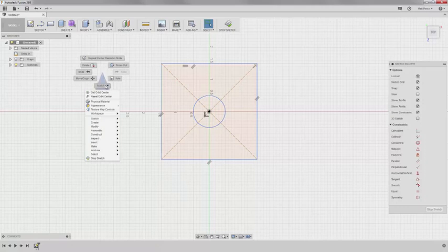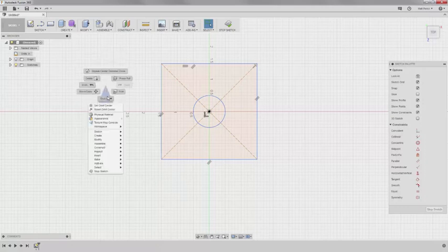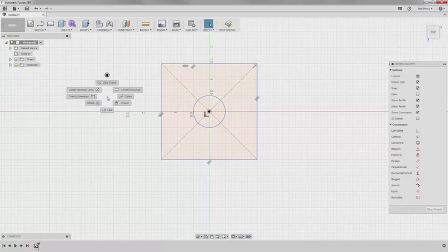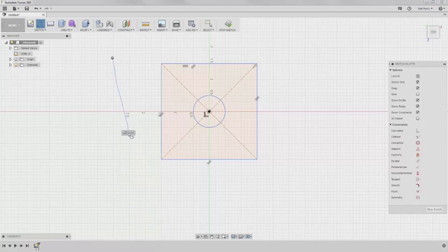If you right-click to use the marking menu, you can move down over the word Sketch to bring up the sketching options and see the Line tool at the bottom position. To make the most of the marking menu, you can simply right-click and drag straight down to create a line. We will start the line at the midpoint of the upper horizontal line and drag down roughly ½ inch, then left-click. Once you place the second point, notice that a green checkmark button appears.